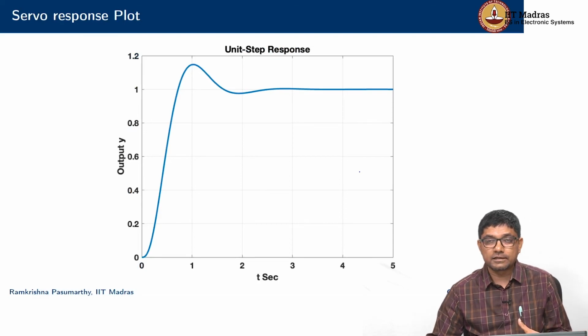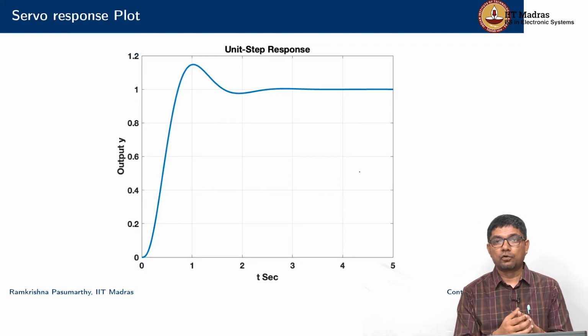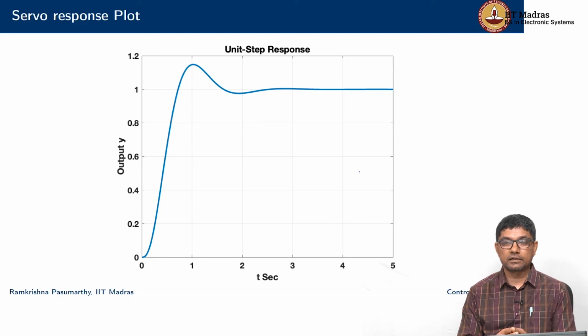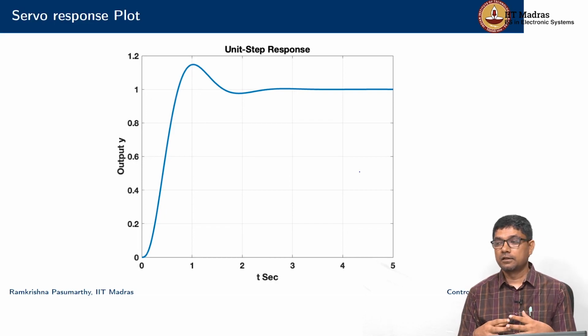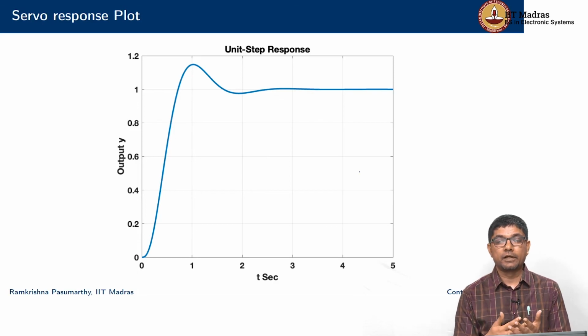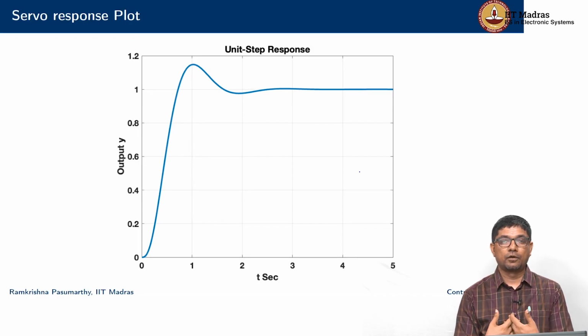So the things that we have done so far are how to place the poles at arbitrary locations, and second, how to even solve some kind of tracking problems. The takeaway here is that for arbitrary pole placement, the system needs to be fully controllable. The same thing also holds for tracking problems, and we had seen 3 methods of how to solve the given pole placement problem.